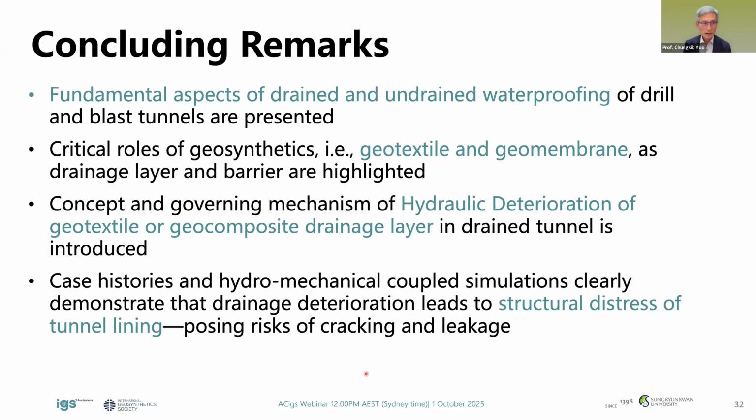So in concluding remarks, in this presentation, fundamental aspects of drained and undrained waterproofing of drill and blast tunnels are presented. And also the critical roles of geosynthetics, geotextile and geomembranes in particular, have been discussed. And the concept and the governing mechanism of hydraulic deterioration has been discussed here.